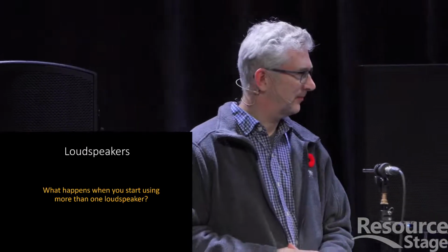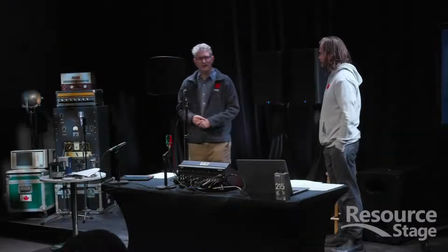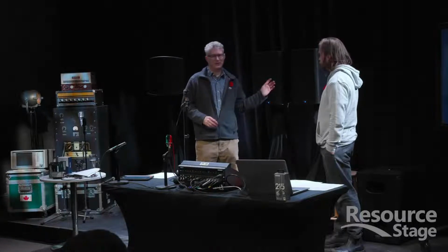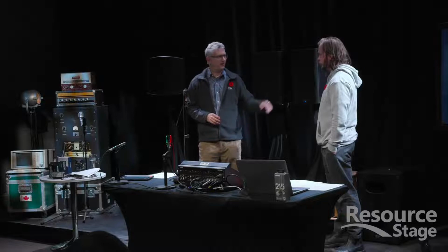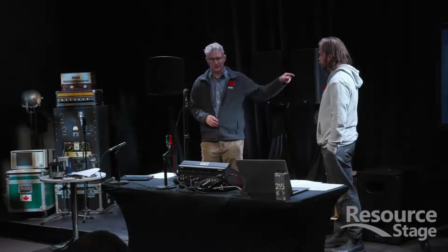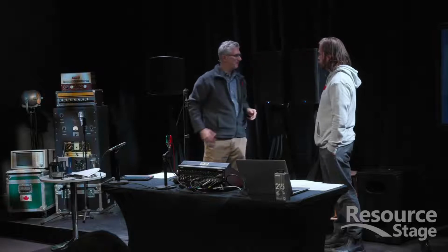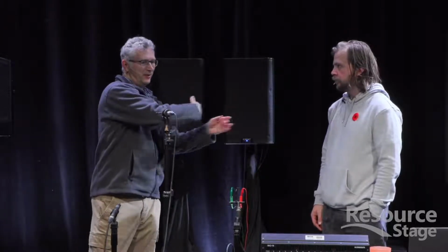I believe you were going to talk about the dispersion of these. Oh yeah, so we talked about these. These are powered loudspeakers. We have two speakers set up side by side. Each one of these loudspeakers is a 90-degree conical dispersion pattern, so it's 90 degrees in all directions. Sitting side by side like this, if we turn on both of these loudspeakers, we're going to get significant overlap between the two.